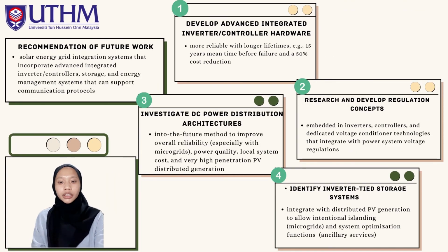Lastly, I will explain the recommendations for future work. Develop a solar energy grid integration system that incorporates advanced integrated inverters, storage and energy management systems that can support communication protocols used by energy management and utility distribution level systems. So first, we need to develop advanced integrated inverter hardware. Second, we need to research and develop regulation concepts. Third, we need to identify inverter type storage systems. And lastly, we need to investigate DC power distribution architectures.